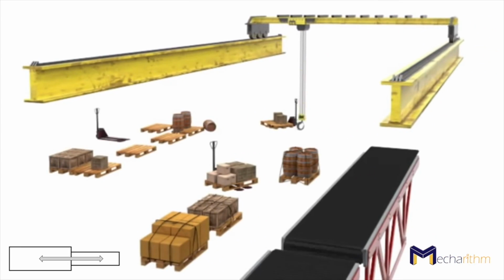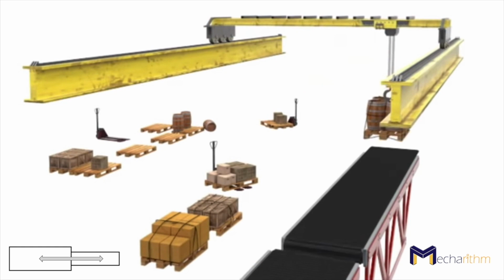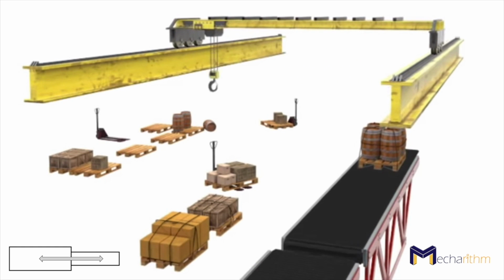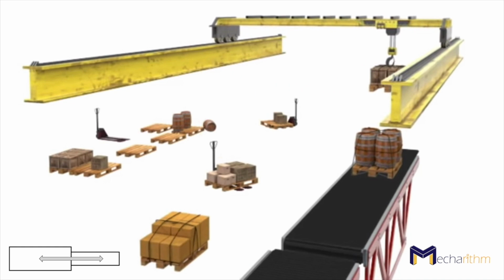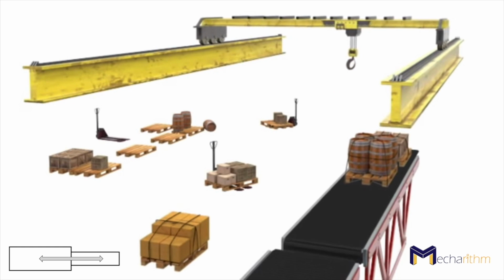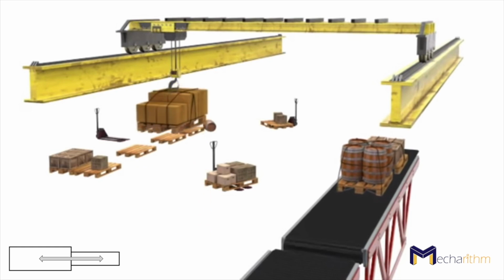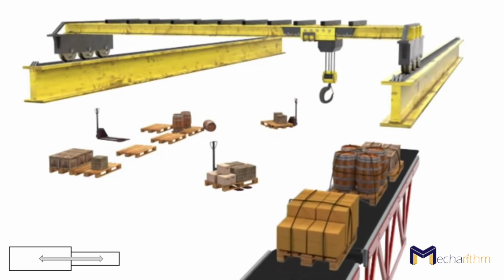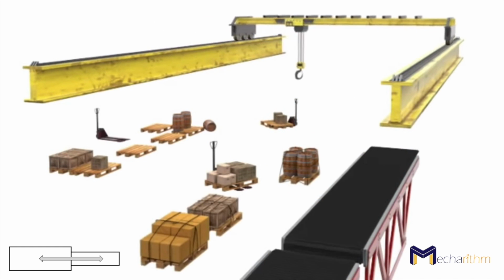A linear, sliding, or prismatic joint provides the linear motion between 2 links. It will again provide only 1 degree of freedom between 2 links. The robot in the picture has 3 prismatic joints, so it has 3 linear degrees of freedom. Next is the universal joint, which is 2 rotational joints that are orthogonal to each other. So it can provide 2 rotational degrees of freedom. These 2 rotational degrees of freedom are around the roll and pitch axes, that are the X and Y axes.